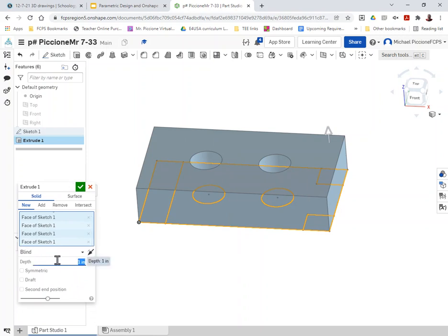And we said that we were going to go 1 7/16, because that was the height of the shelf. And then we can subtract 7/16 from that. I could have also gone up 1 7/16 for the height of the shelf. I could have gone down and gone up. It doesn't really matter in the direction you go when you're doing your extrusions. The goal is just for you guys to learn how to do different techniques.